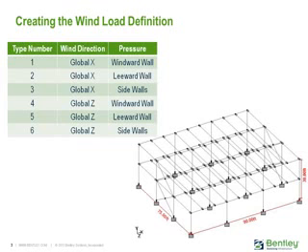For our sample model, we will be creating the wind load definition, and we should consider the windward, leeward, and sidewall pressures in each of the global axis directions.